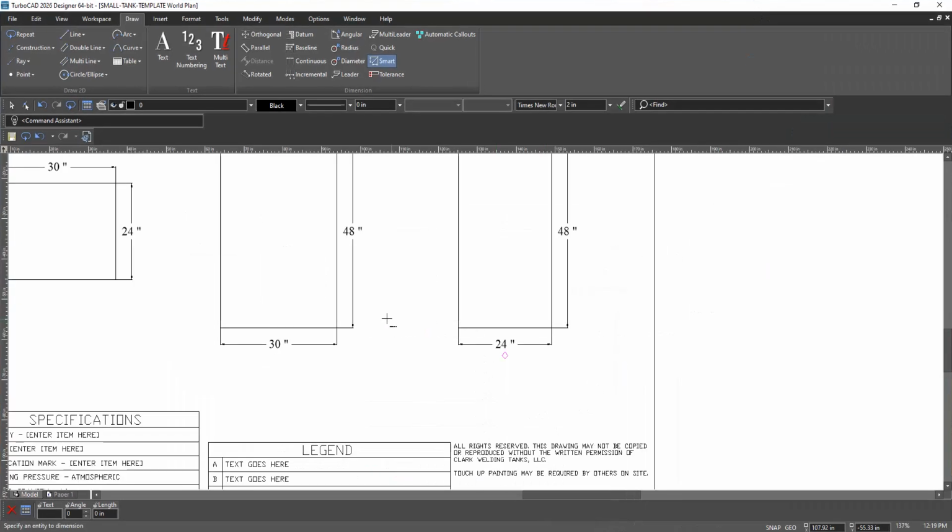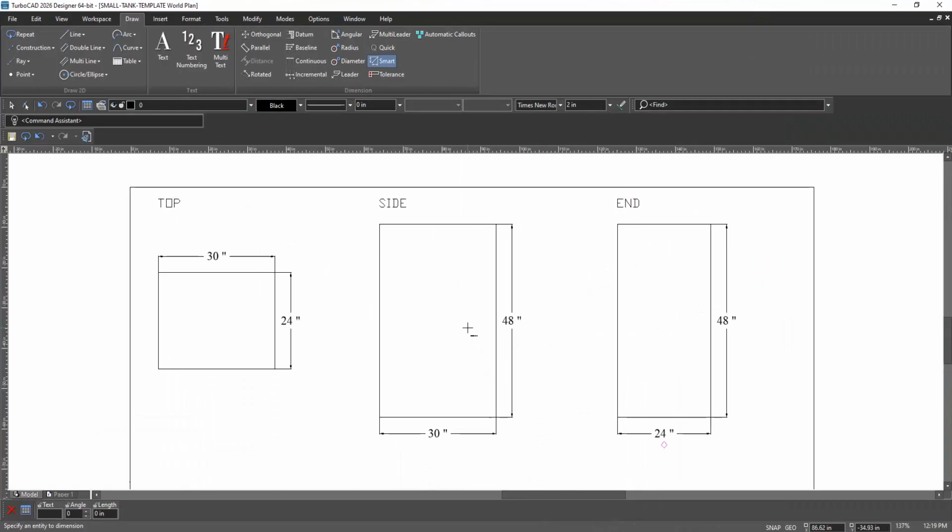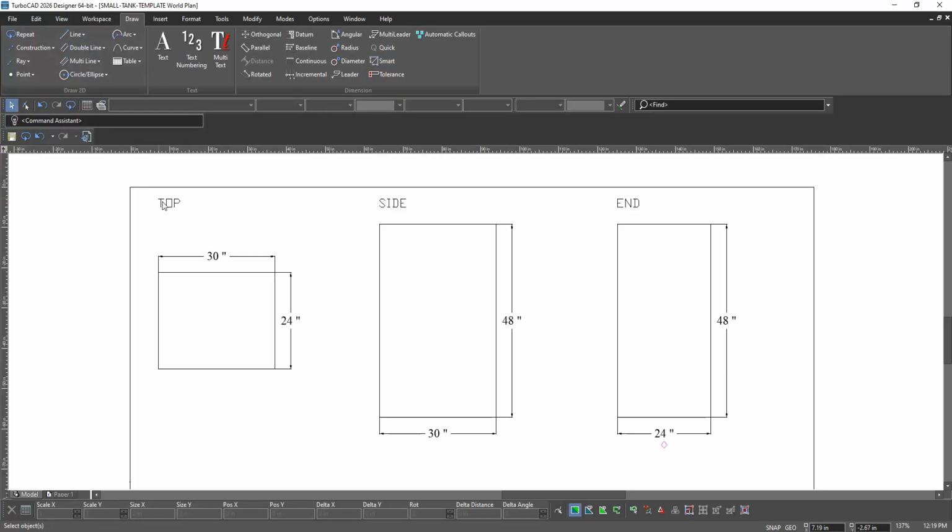And the next thing that we want to do is we want to set the proper font. So we're going to go back to our select arrow, and I want you to hold down the shift button on your keyboard this entire time and do exactly like I tell you to do.